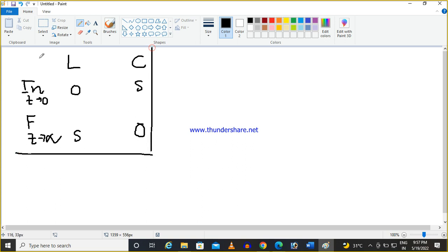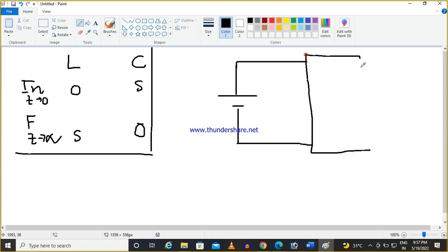Why I am telling this is because when you are making the inverter, this is your DC source, and this DC source will be switched at very high frequency. This DC will be switched, which will generate AC. This will go to the load. So now you can understand, if switching, on and off, is taking place, suddenly we are making and breaking the current flow at very high speed.